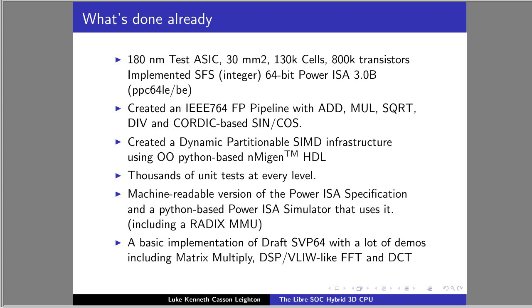When we're testing the core, which puts all the function units, the pipelines together with a register file, where the register file had its own unit test as well, back down in its levels, the core gets its own unit test. And then when we add an instruction issue to finally create a final top-level core, then you can run all of the unit tests amalgamated below all those levels again and again. So we end up actually with 4 different ways of running the exact same unit tests to make sure that everything's still functional.